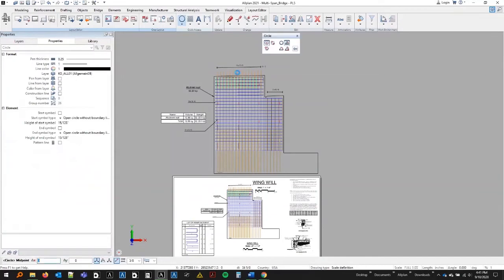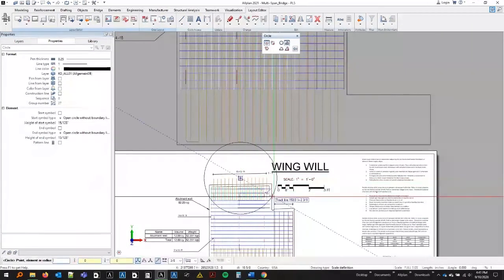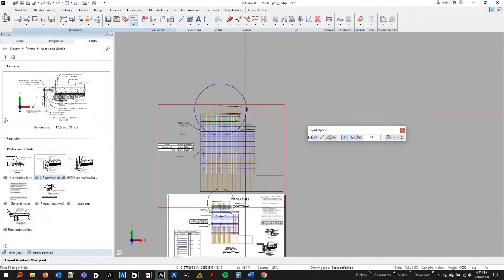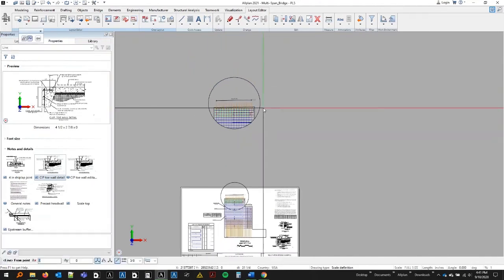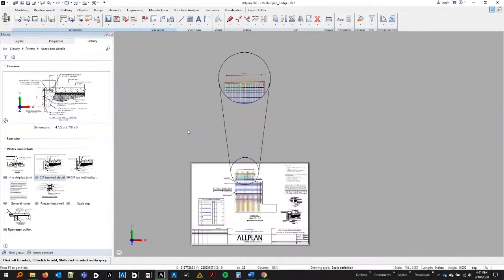All right, so now I'm going to cut this viewport with any polygon I want. I'm going to use here a circle, so I'm going to do a similar one down below to indicate, like I said, this call out here. And I simply select my second layout and then that first circle, and then it's using that line to create a polygon that it will then cut. And then for the human eyes, you might draw a few lines indicating that this is an expanded section of the one below. And so as you can see, this is a lot of the CAD functionality, a lot of the CAD workflow that you're already used to. It's just bringing a bit of automation to your daily routine tasks that you guys are always doing.